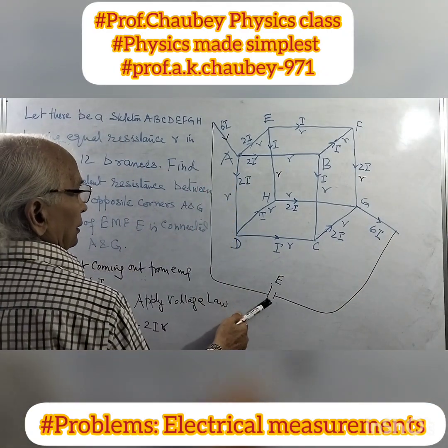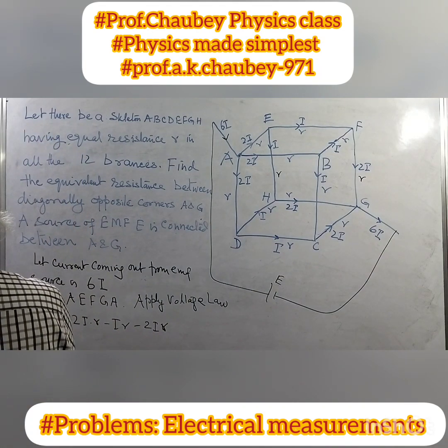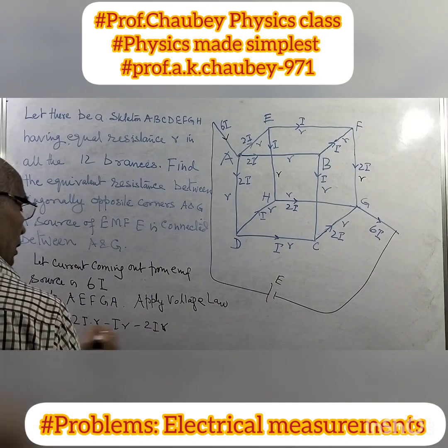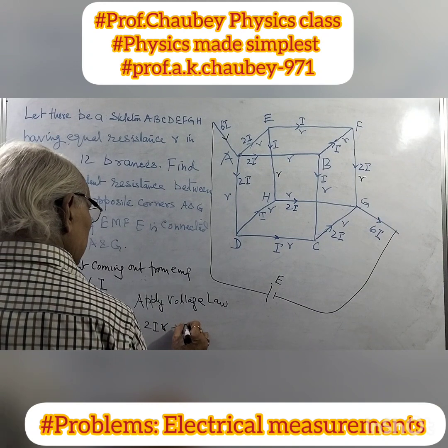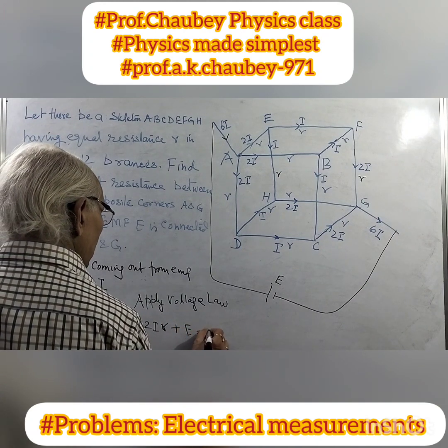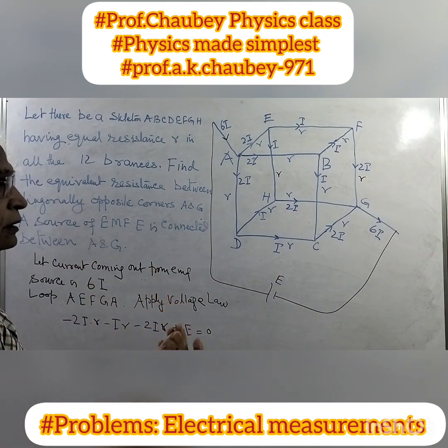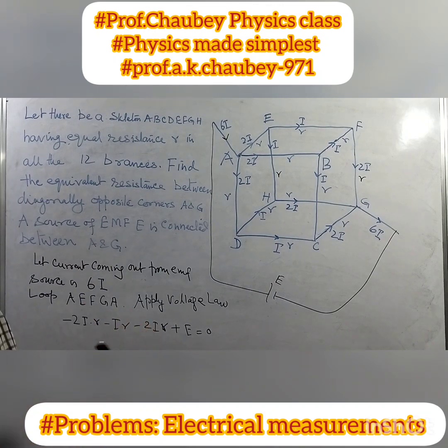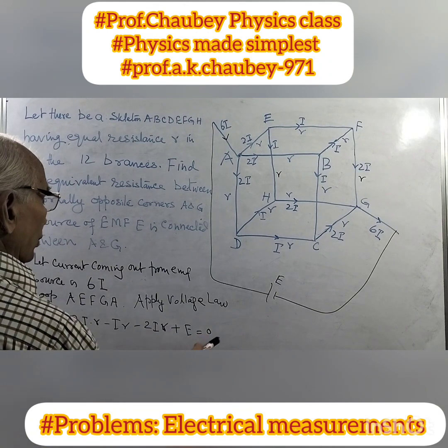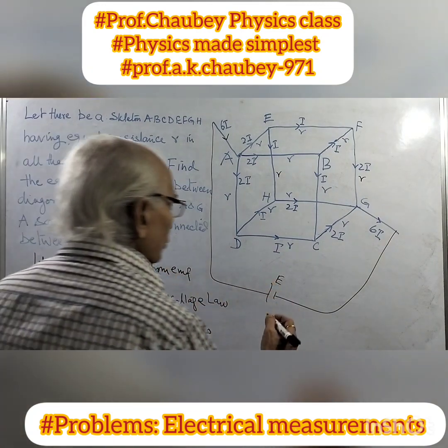A battery is connected here, so this is the applied source. This is the voltage law equation: all the IR drops plus E must be 0. That is for the conservation of energy, total energy supplied and total drops must balance. Energy is not accumulated. So the applied voltage E must be equal to the IR drops. You can write it like this.